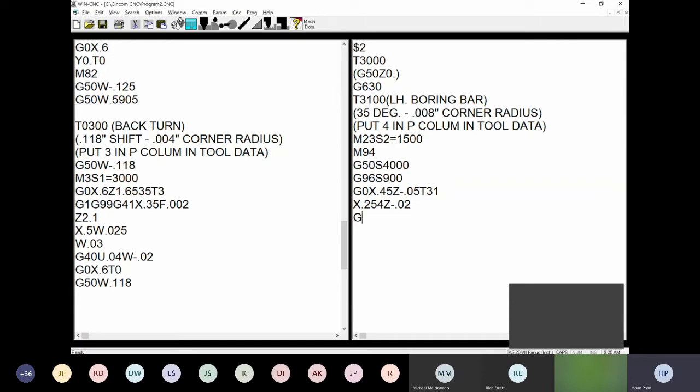And then Z, I want to get close a little bit right there. And then right here, I can start using tool nose compensation, Z0 with the feed rate 0.001 and a half right there. And then I can go up and then make a chamfer. Oh, so somebody tells me that okay, we need to start using the comma C or comma R, something like that, with the radius. So I'm gonna use it now. So maybe let's leave this thing right here.